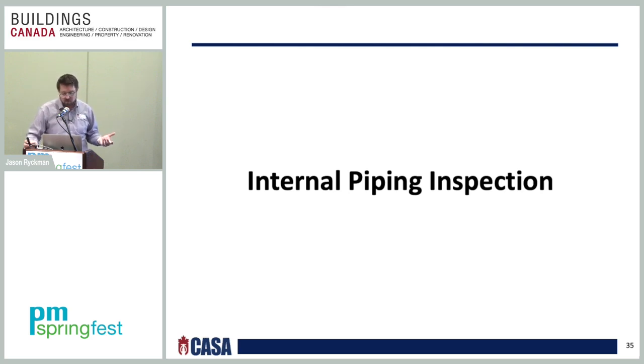Sprinkler systems are no exception. Any maintenance program must include means for revealing potential obstructions and removing any obstructions that exist. Obstructions are addressed in Chapter 14, which identifies potential causes of piping obstructions, and requires an obstruction investigation, which is different from an internal piping inspection, which we'll get to a little later, if any of those situations exist.